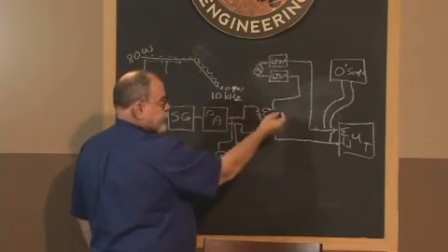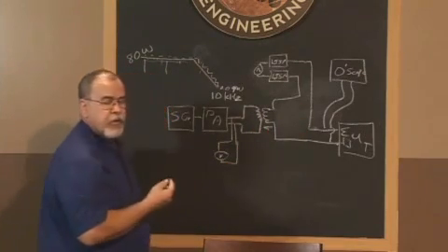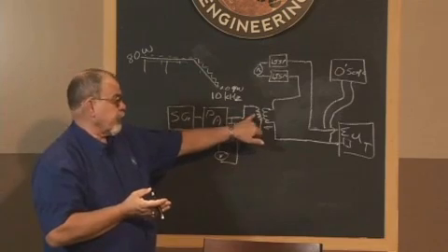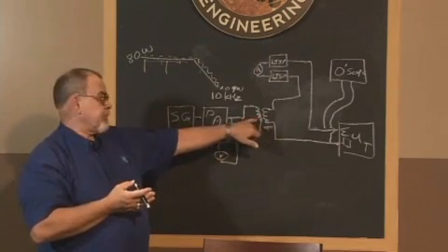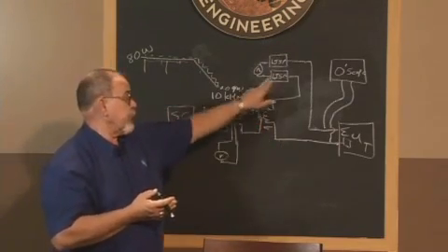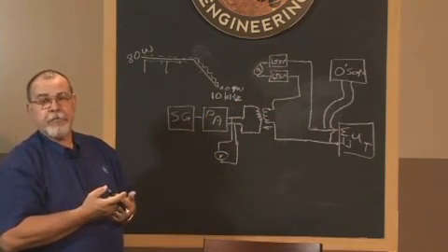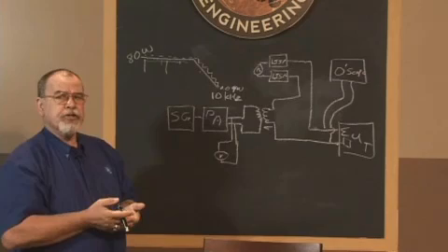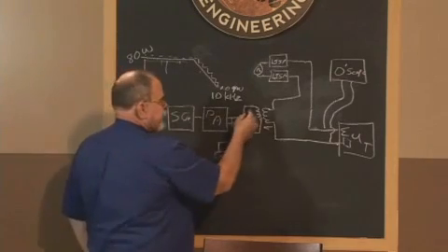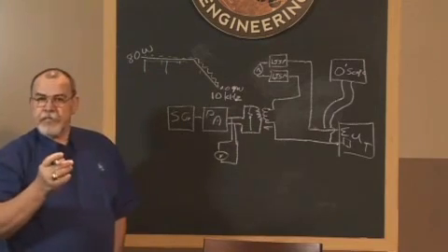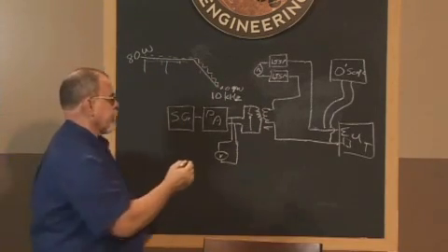Depending on the impedance and the current draw of the equipment, we may have trouble getting the test article to actually start, because this reflected impedance will show a high impedance and prevent current flow in our circuit, so our unit never gets the power to start activity, especially if there's a high inrush current. So we may need to temporarily connect a resistor here to provide the startup current, and then we can switch it out.